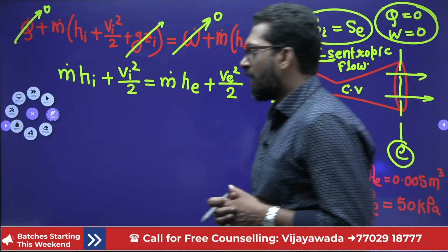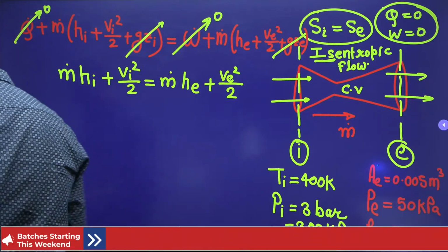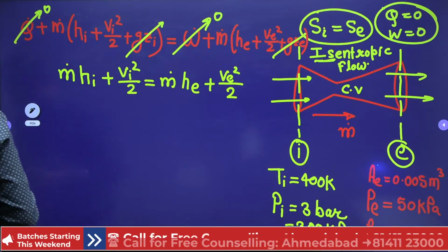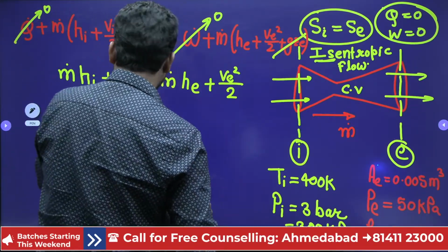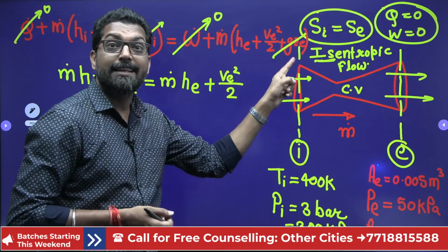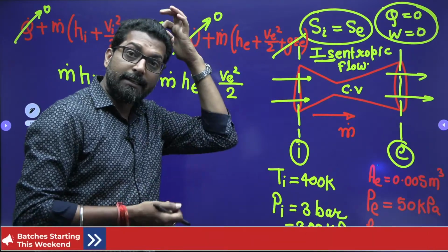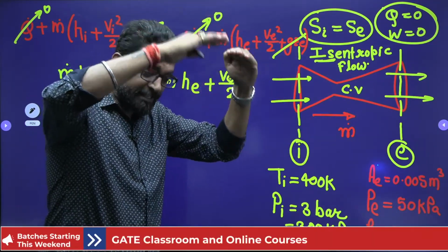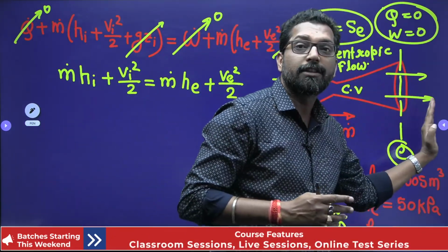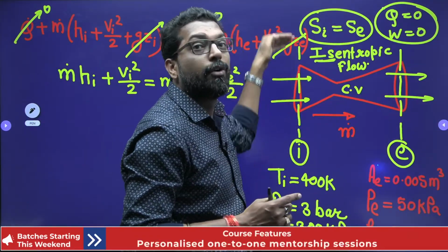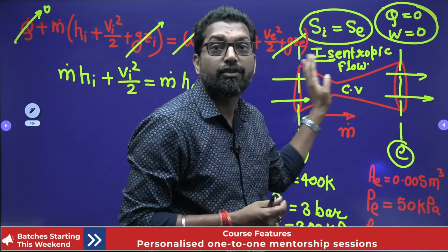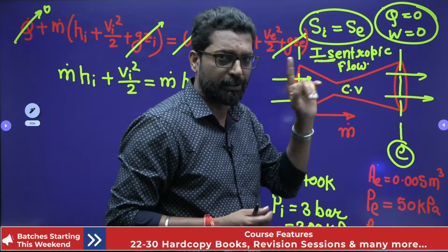Okay, so we have to find this. Now there is no information given. See, this end is placed in the large tank. So the change in the level in the large tank is very slow as compared to the exit velocity. That means the inlet velocity from the tank is very, very less than the exit velocity, because it is installed in the large tank. This is very important.